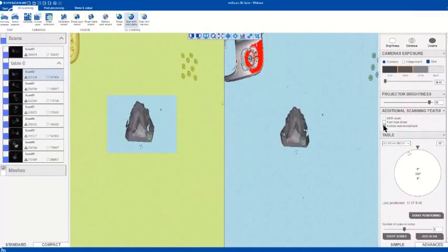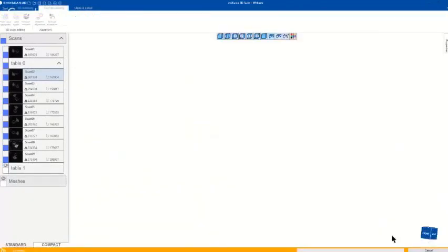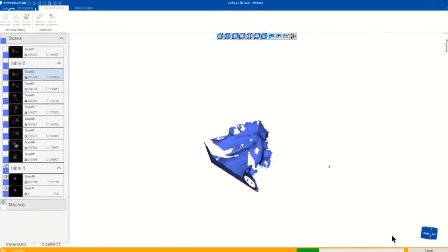For the automatic alignment between the scan groups, I need to check the functionality called include markers artifacts. In this case, when I start the series and make another one, both series, or many more than 2 series, will be automatically aligned to one coordinate system, which will be located on our unique marker, or of course the artifact.